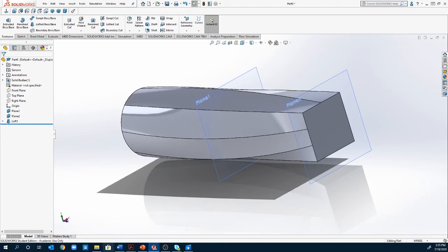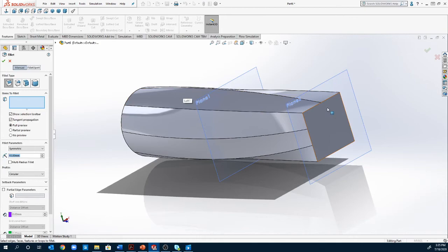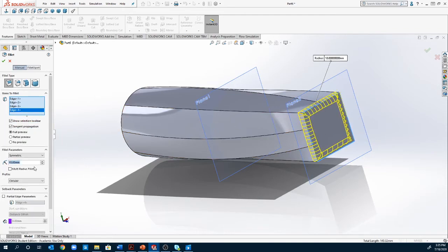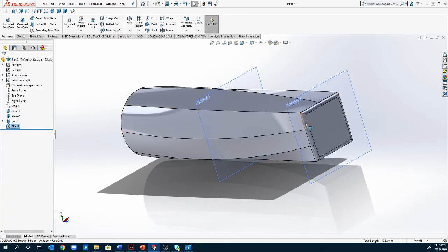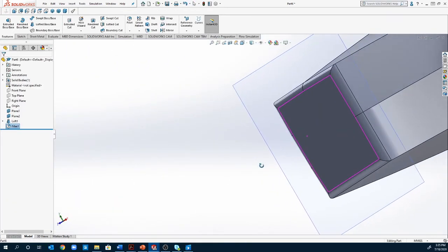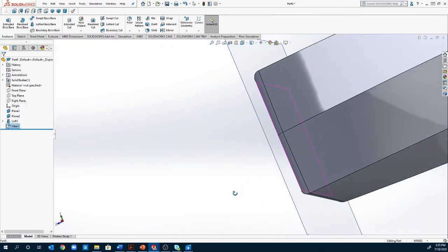So now a couple of things to do once we have drawings, or models. One thing we can do is use the fillet tool, which is going to allow us to round edges. So we can come up here and round, and round, and round, and round. And we can set the radius. Right now our radius is 10. Let's change it to maybe 5, because we want a little bit less of the effect. And we're going to say OK. It's going to make a smooth edge on that so it's no longer sharp.